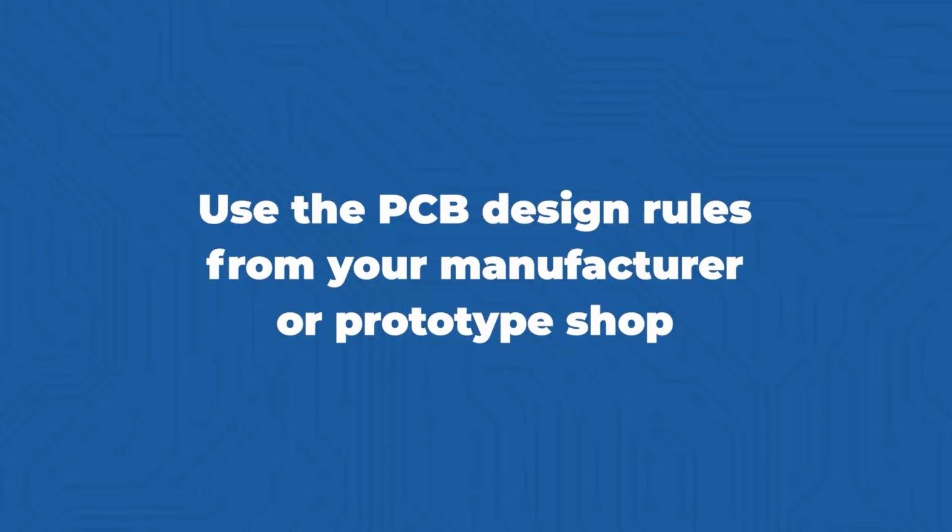I've found that prototype shops can do custom rules, but they also typically will have price discounts if you follow an easier to meet standard, like where the minimum trace width is really wide, and then the spacing is larger, so you can get a discount on that. But typically, if you go to a manufacturer, they can meet a lot. They can kind of customize the process to match the rules that you've used. But in general, start with where you plan on having these prototyped and look up their design rules and be sure that you enter that into the software before you start on the design.